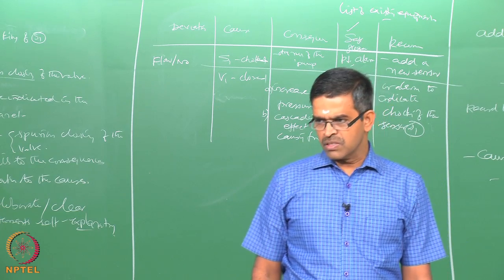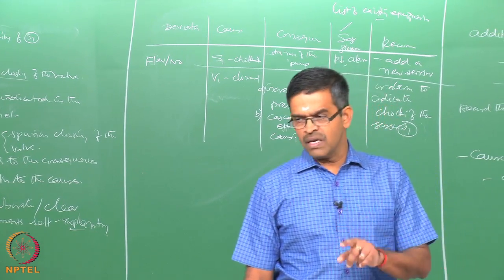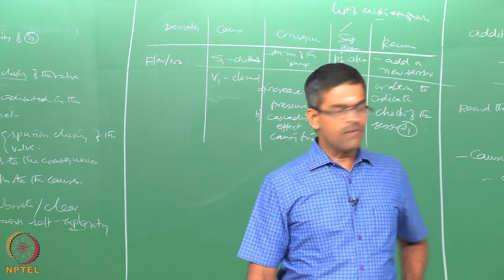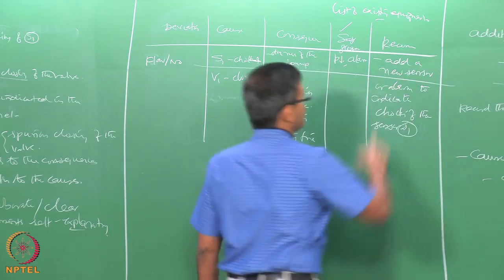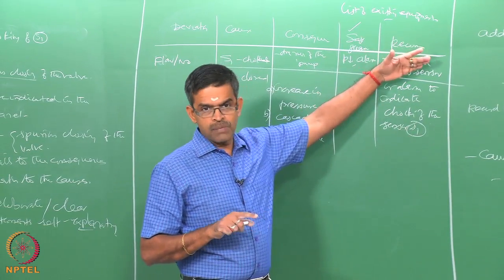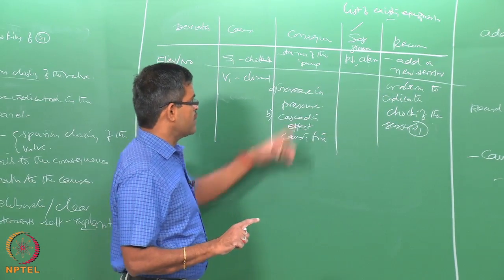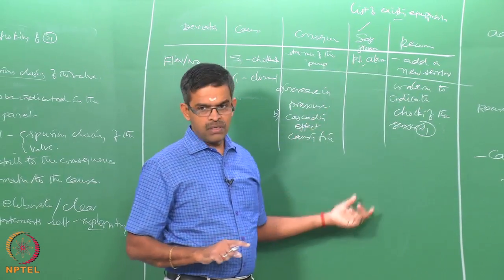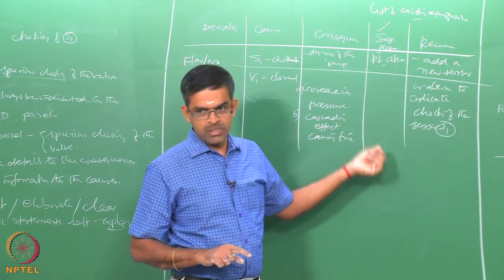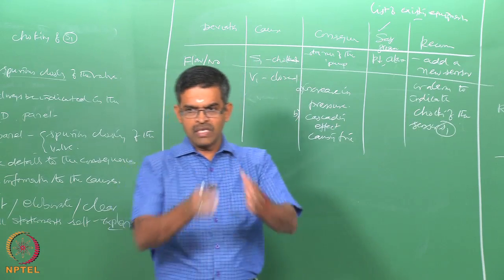So, if a credible cause results in a negative consequence, it must be decided whether some action should be taken, along with its priority. Therefore, when you give the recommendation column, you also have to give the priority of the recommendation: which is the foremost important, which is the least important. Similarly, when you identify the safeguards, you must acknowledge the one which is actively present and the one which is not actively present. You must indicate all the safeguards present in a given system with detailed explanations.